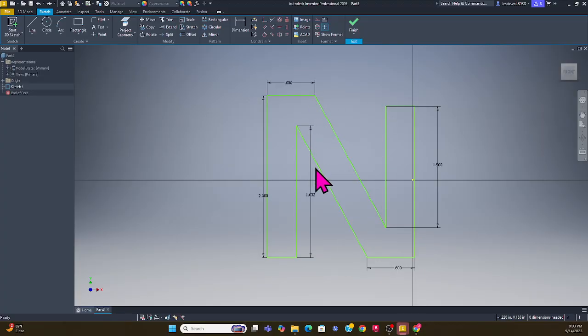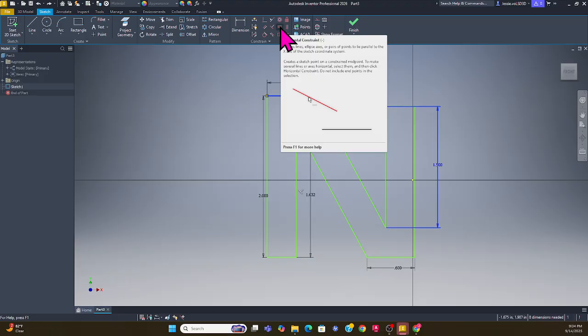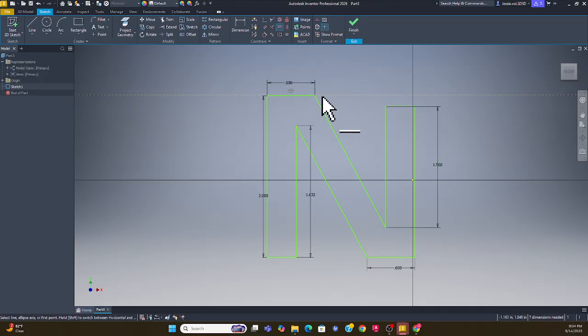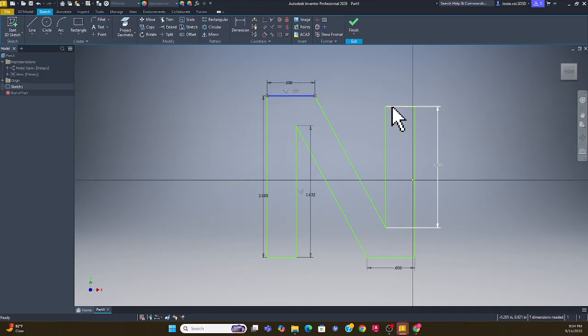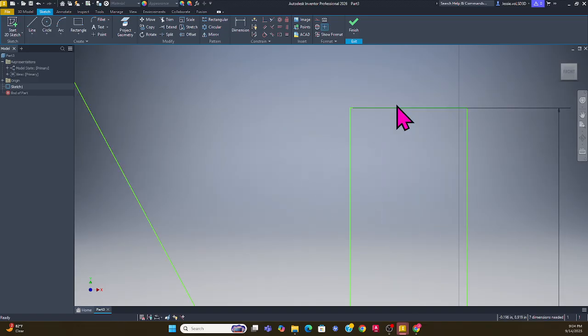I'm going to click on this line segment, hit the shift key, and click this line segment, and I'll constrain this to be, hit escape again, which one is going to be collinear? This right here, I believe. Yeah. Collinear means it's going to be on the same line. I need to select the line segment again. I'm going to zoom in.